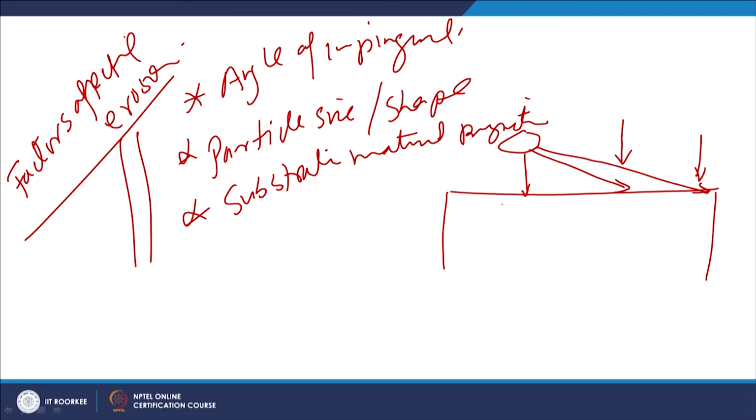So, if we consider the extent of the indentation which will be formed in case of the soft and ductile material, that will be deeper, somewhat shallower and further shallower in case of the low angle impingement, because the effect of the impact on the low angle impingement is less under identical conditions of mass and velocity of the particle.